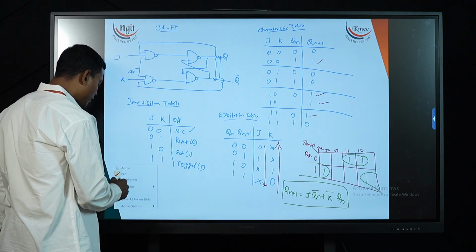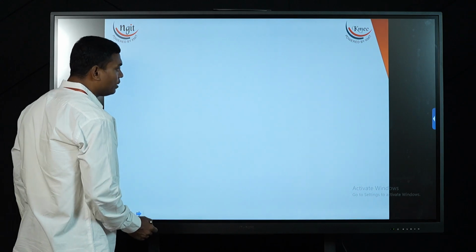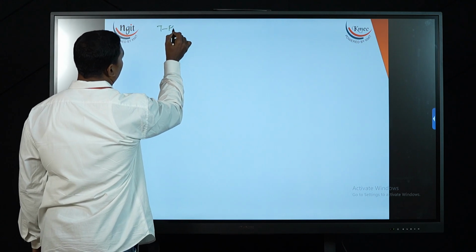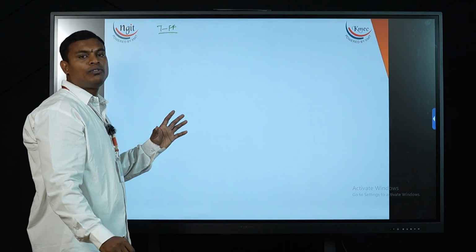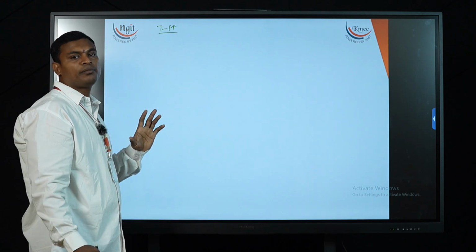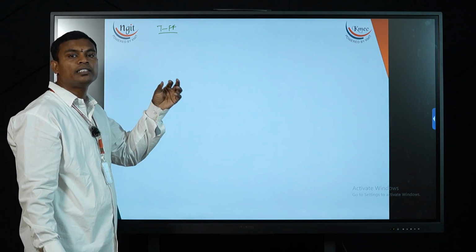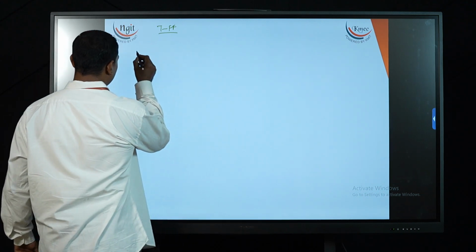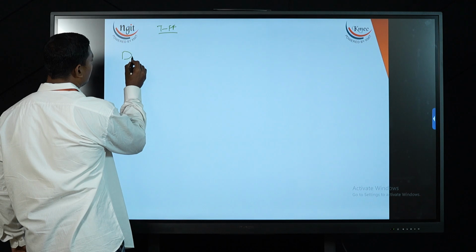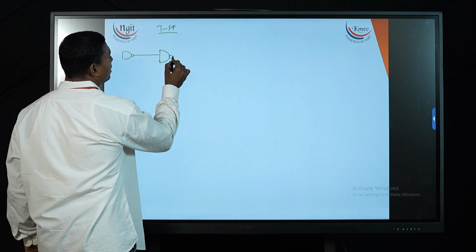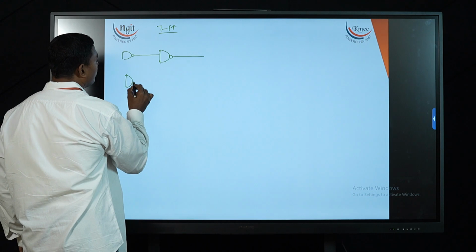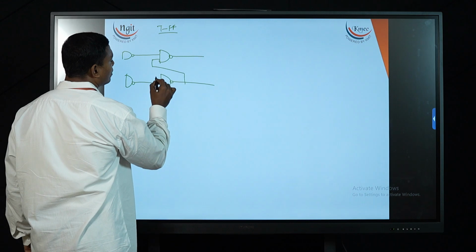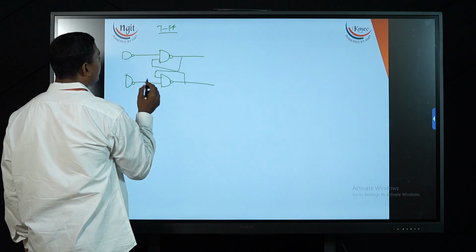Okay. Let's get into the next flip-flop, that is T flip-flop. T flip-flop, right. Now T flip-flop is here combining J and K terminals. For D flip-flop what we have done, we connected S with R using an inverter there. Here directly we are going to connect the values here. Now observe it clearly. This is my NAND gate, this is my NAND gate, this is one more NAND gate, this is the other NAND gate. I am having a cross coupled connection at the output level, right.